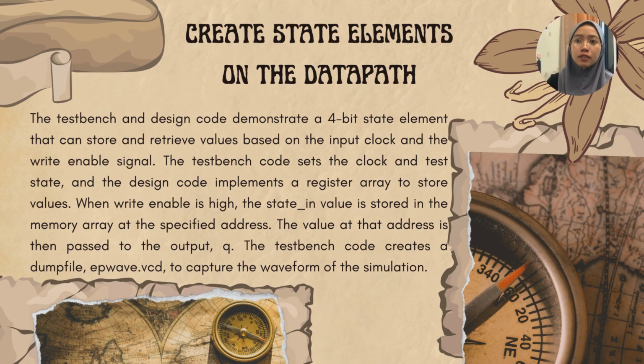For create state elements on the data path, the test bench and design code demonstrate a 4-bit state element that can store and retrieve values based on the input clock and the write enable signal. The test bench code sets the clock and test states, and the design code implements a register array to store values. When write enable is high, the state-in value is stored in the memory array at the specific address. The value at the address is then passed to the output Q.